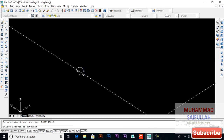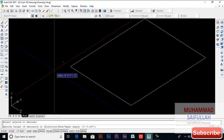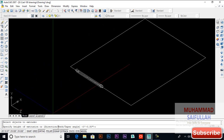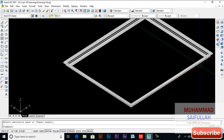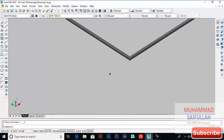EXT for extrude, select object, enter. So if you extrude it straight, this will be the problem. So I will have to give it a path, P for path, and I will select this path. So our shade is created. If you see,